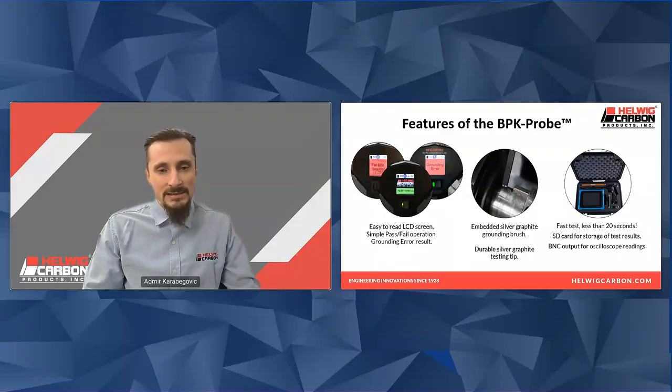We do have embedded silver graphite grounding brushes and a durable silver graphite testing tip. So our kit has 2 silver graphite sliding contacts, one that is the sensing brush that senses the shaft voltage, and the second one can be activated to act as a shaft grounding brush.